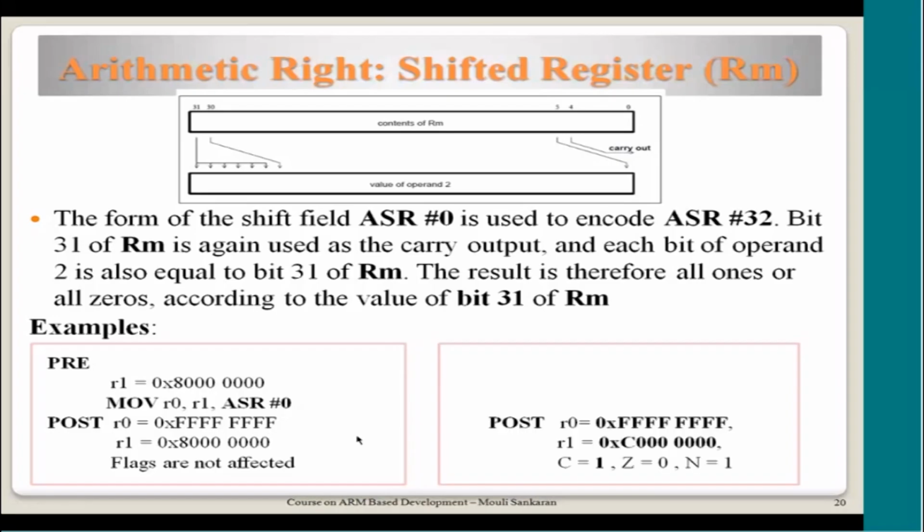Okay, let us see one more example. Suppose MOVS is there and R1 is filled with... please remember I am taking only R0 and R1. It doesn't mean that you can do it only with R0 and R1. You can do it with any register, please remember. But R15 is always a special thing because it's the PC, but you are free to use R3, R4 or R5 or any operand. It could also be the same operand. You can say R1 comma R1, no problem.